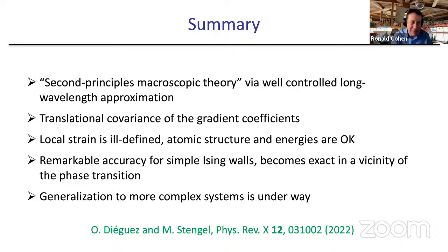Well, let me just follow up on that myself, and then we're going to have to wrap up because we're out of time. This goes back to classic work on elasticity. For polycrystals in ceramics, if you consider constant strain conditions or constant stress conditions, you get two different mechanical behaviors, and reality is somewhere in between.